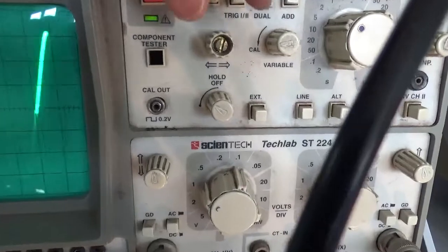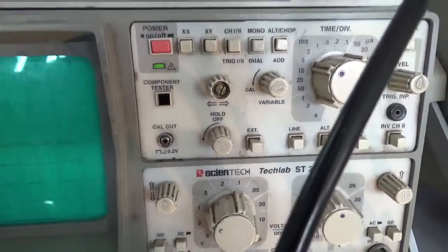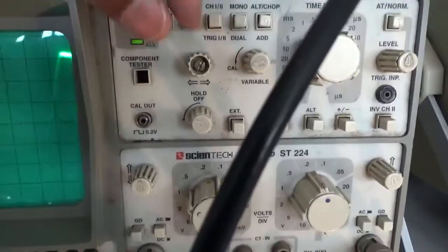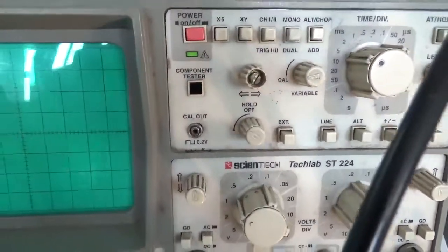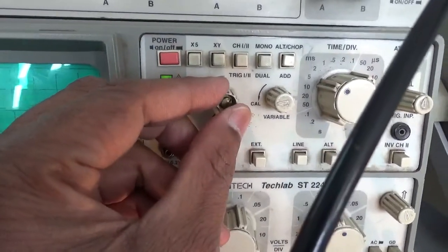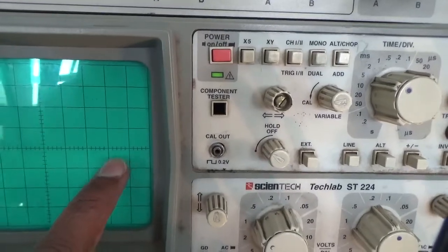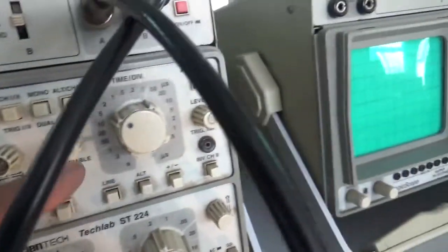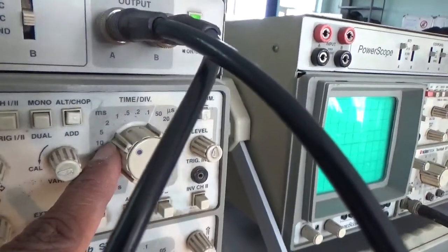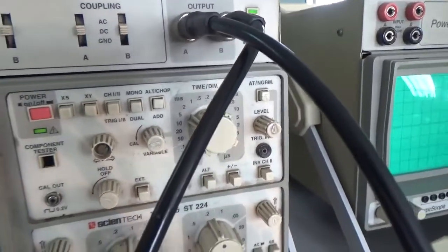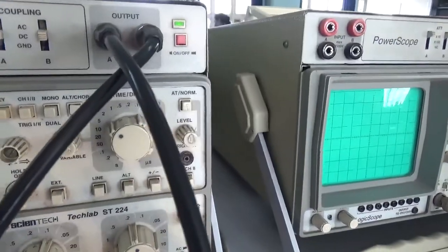Frequency measurement. For frequency measurement, keep this from the 0 reference and see how many units you take along the x-axis. So let me keep it at the 0 reference. It is 1, 2, 3, 4. 4 units into 5 millisecond, so 4 into 5 millisecond is 20 millisecond. For all the AC voltage measurements in power electronic converters, you keep the time division at 5 millisecond.